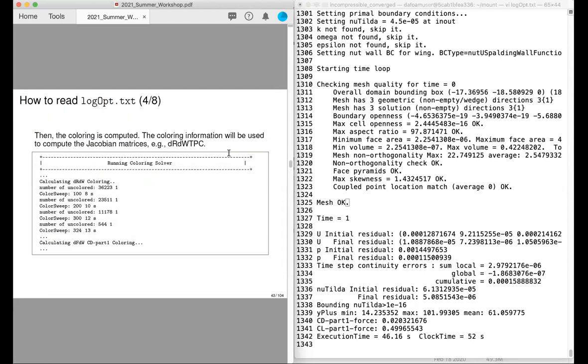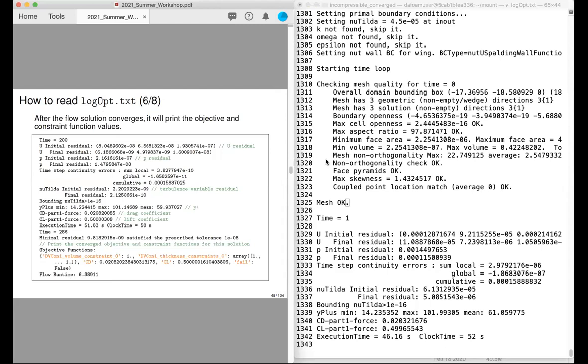So DAFoam has the option to relax the checkMesh threshold. Right now, the default value is, I think, 70 degrees for the orthogonality and 4.0 for skewness. You can relax this. You can say, I can accept non-orthogonality being greater than 75. There is an option to relax that.